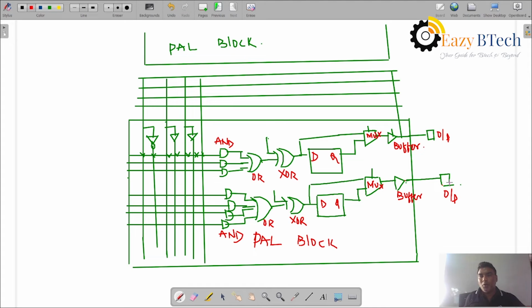Input output block. So each PAL block representation is programmable, internally designed. This is one structure of a CPLD, a diagram or figure representation of a CPLD PAL block. So this is one structure of a PAL block, and it is programmable from the interconnection.